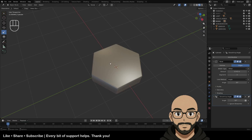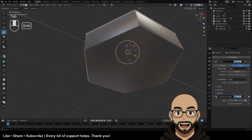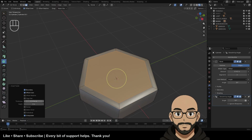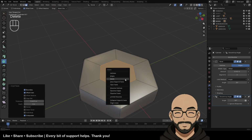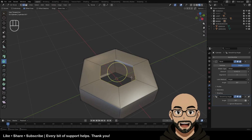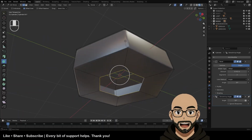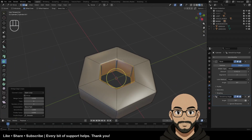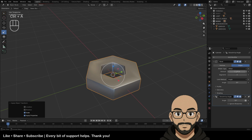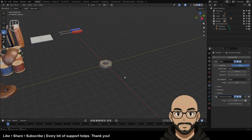Now we're going to put the inset, so we're going to select the top face, bottom face, inset. I'm going to drag the value from here. I'm going to delete these two faces. I'm going to select the inner loop, the inner edge of this loop, and then the one underneath, the one there, so other side. And we're going to bridge those loops together. Boom. I'm going to hit Control A, apply that scale again, and then we're going to adjust our bevel on there. Like I said, it doesn't matter too much on there. Now we have a bolt.